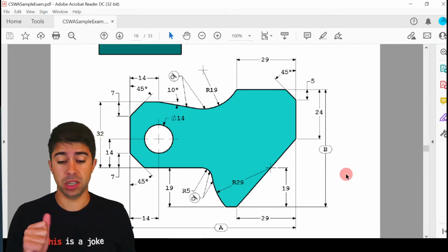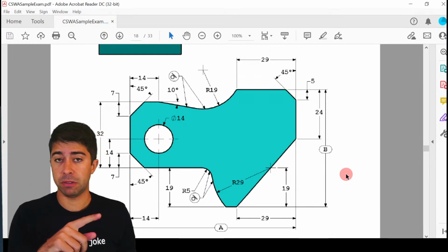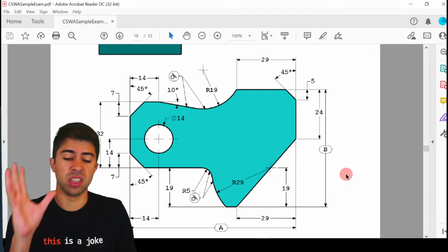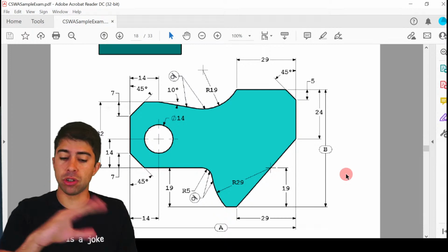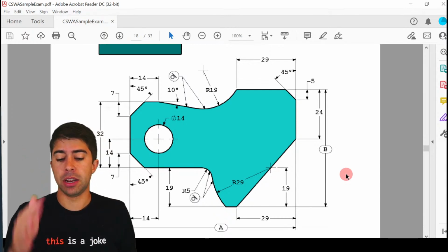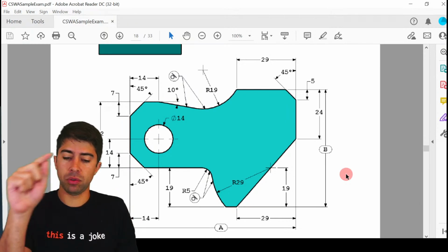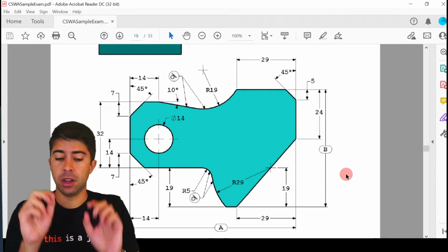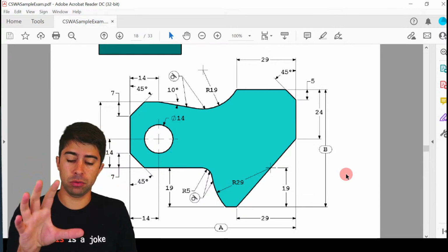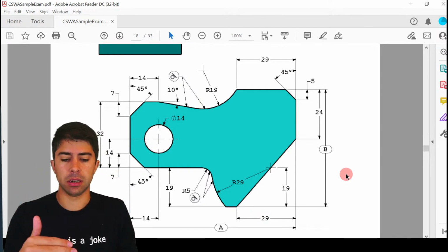In FreeCAD, I guess it's a bit easier, SolidWorks. But you sort of draw the rough outline of the part first. Don't put any dimensions in, don't put any relations in, just draw the rough outline. And then you start at a point and you start adding all the relations, all the dimensions, and you try and mimic this part or this sketch with all the dimensions, so that when you compare this PDF and your FreeCAD or your SolidWorks drawing, you can see where dimensions are missing because you've positioned them in similar positions.